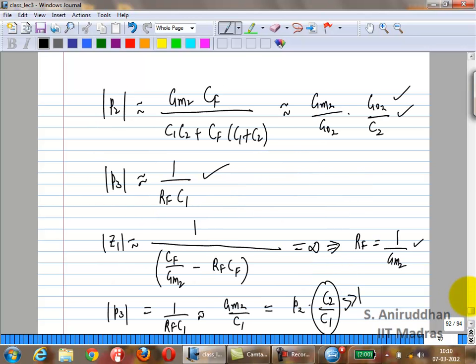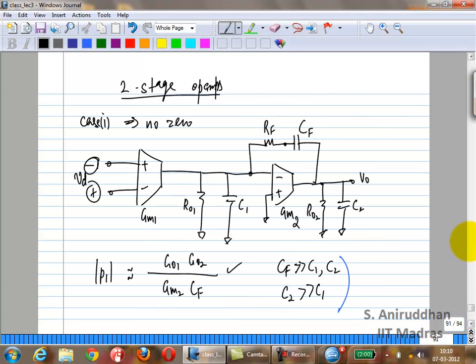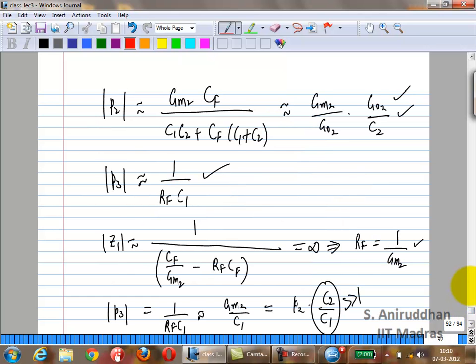So we wrote down the poles and zeros. We added one big difference from the previous case. We added a resistor in series with the capacitor. So now what that does is it moves your zero to a new location, and it also adds a third pole. Those are the two big differences by adding that resistor. You add a third pole, which on first glance looks to be quite far away. And the zero itself we can manipulate using RF.